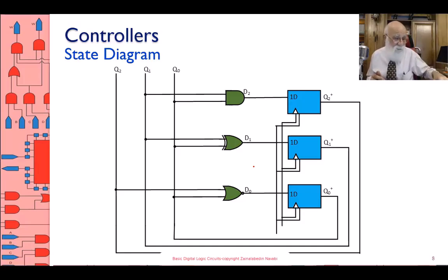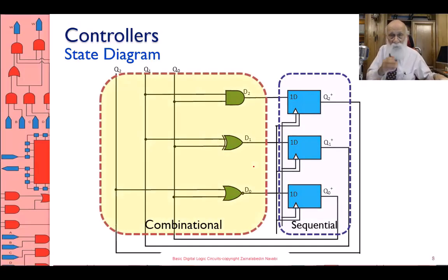This design has a sequential part, a clocking part, and also a combinational part. So what I'm saying is, if my first step is a state diagram, then going from the state diagram to the transition table, to the table for the D flip-flops, then to the Karnaugh maps, and then to the circuit diagram is an easy, procedural thing. So let's now focus on the state diagram.